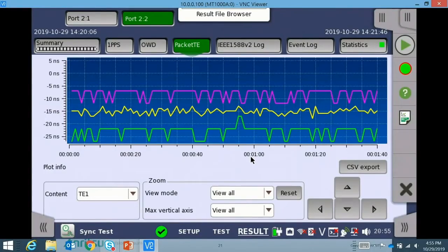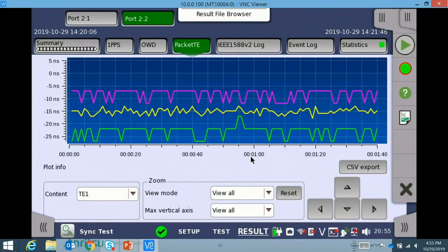So as I mentioned, when we're looking at this, what is this telling us? Depending on how we set up our PTP, we can get anywhere from, I mentioned, as low as 16 frames per second, as high as 256 frames per second. And each one of those frames are going back and forth between the clocks, the grandmaster and that of the slave or the boundary, and it's telling it to adjust its timing, plus or minus. We're taking the average of those every second, and we're determining how much of an offset or timing error we're seeing here, which is an average of 15 nanoseconds.